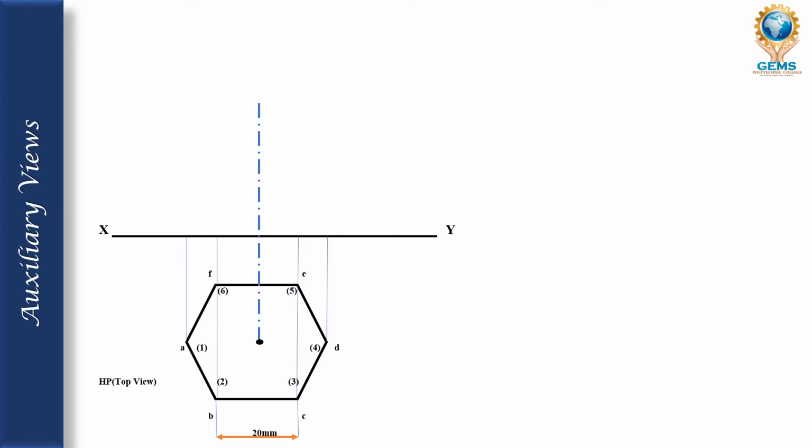Okay, it is the XY axis, so the XY line. Finish on the line. These are 4 lines plus the center line of the prism. Okay, so now you are going to draw the front view or the vertical plane of the hexagonal prism.